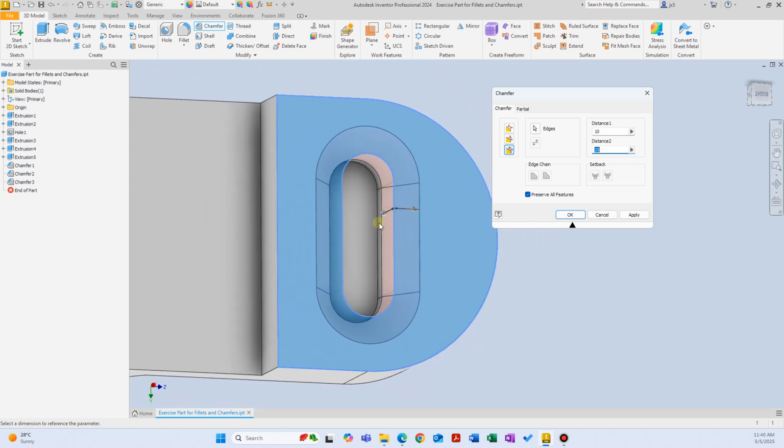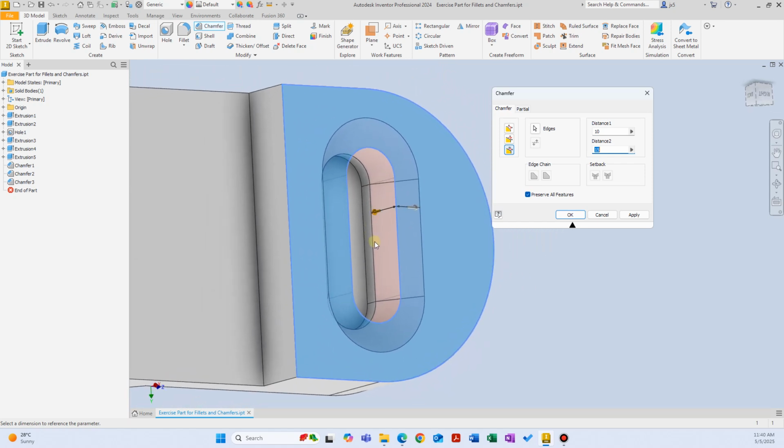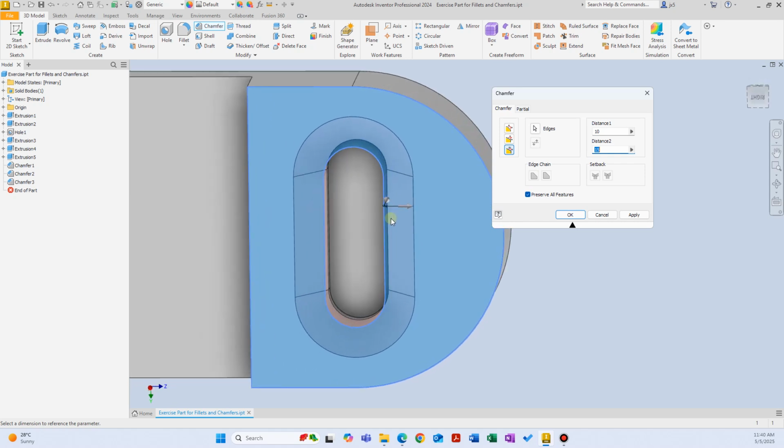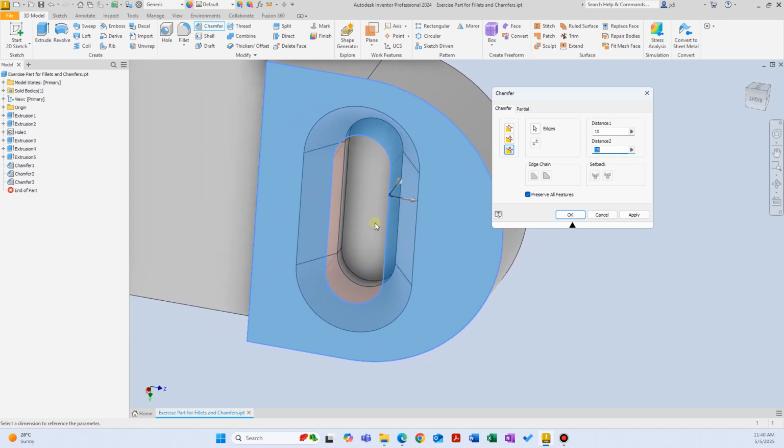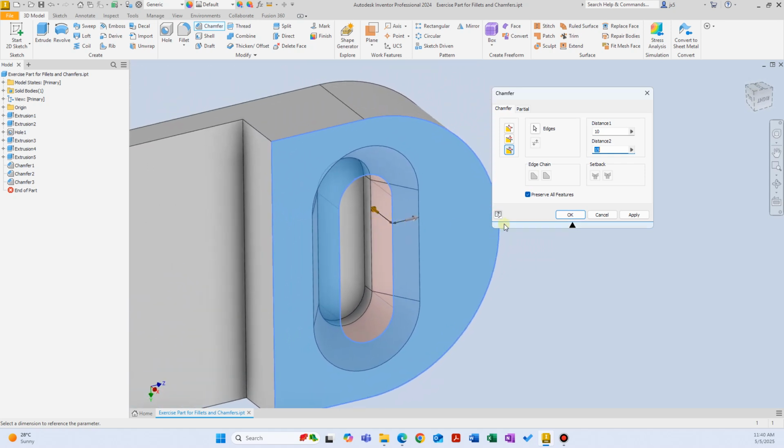I remember that I used this for a project before where I had to design a charging port, and the charging cord had this plastic cover, which made it difficult to go in, and that's why I had to use this feature, this kind of chamfer, to open up some room for that cord covering.